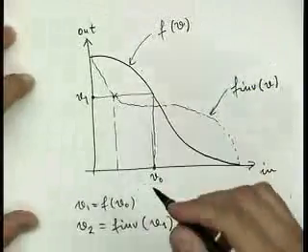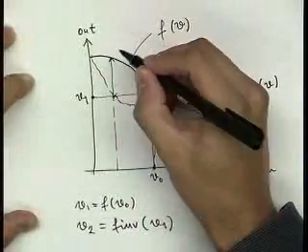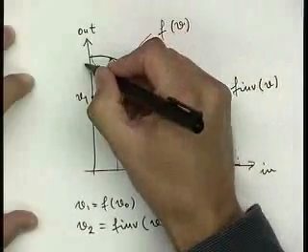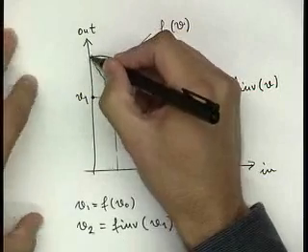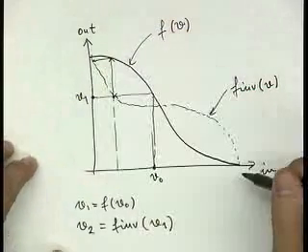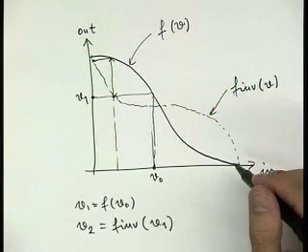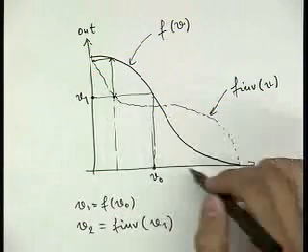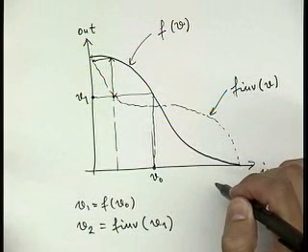And then you continue forward, and then you go to the next stage. You have V3 and so on. So you basically converge to either logic 0 or logic 1. Depending on how many stages you have in this circuit, that defines if you end up with logic 0 or with logic 1.